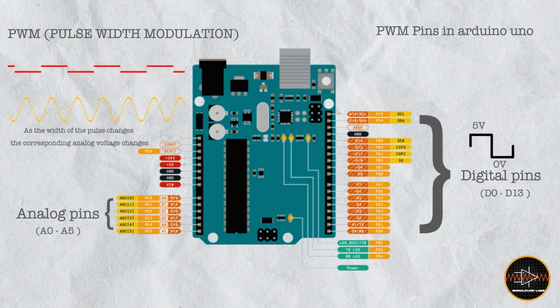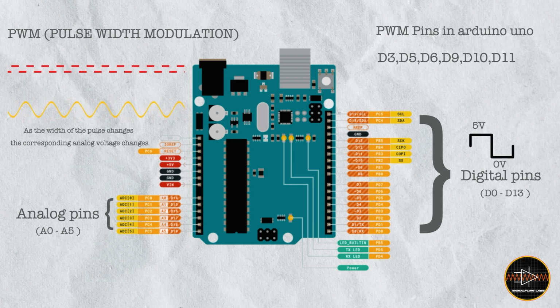There are certain pins in Arduino Uno that are available for this. Those pins are 3, 5, 6, 9, 10 and 11. So in total there are 6 pins for PWM pulse. Now for the frequency that we get of the digital output on PWM, there are different outputs available. 480 Hz is the default setting that is used. All the rest of the pins give 480 Hz as PWM, but pins number 5 and 6 give 980 Hz of PWM output. As you can see on the screen, all these things are available, and you can get to know what digital and analog pins actually mean and how we can use them.